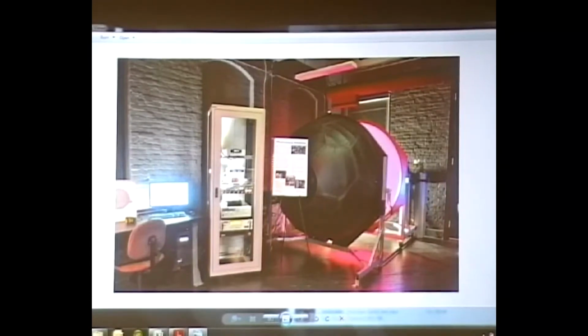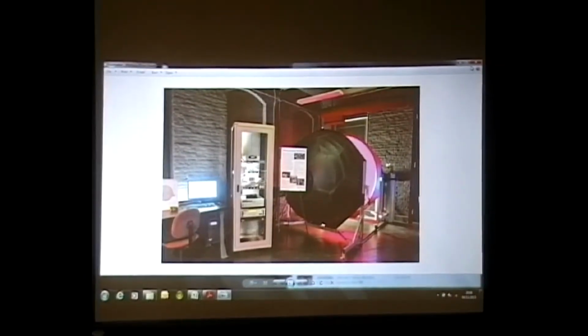Lux is used mainly in lighting, and you'll see the engineers go around with a light meter that tells them the lux, and it will depend on how high the ceiling is, how far away the luminaire is, but they have to have a certain amount of light, usually 1 metre above the floor, so that when the room's full of smoke and you're trying to find your way out, that's the minimum amount of light.